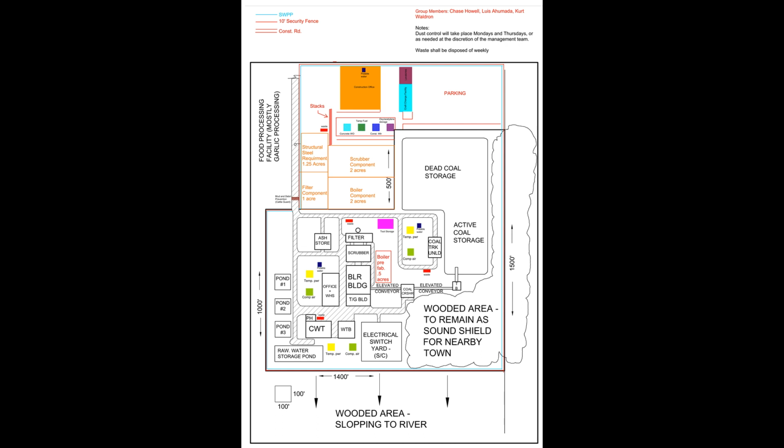Okay. Thanks, Chase. So on the perimeter of the job site, that's just on the outside of the security fence, you'll notice there's a blue line, and that's for us to comply with our SWPPP regulations. It's a silt fence that goes around the entire perimeter of the job site. Notice there's 3 different locations on the job site that are compressed air. The reason we have 3 in those locations is so that the craft personnel aren't running their airlines through the whole job site, just to kind of keep it clean and organized and safe.